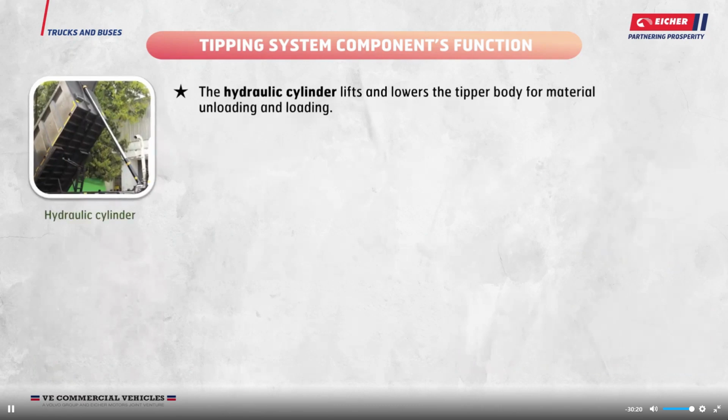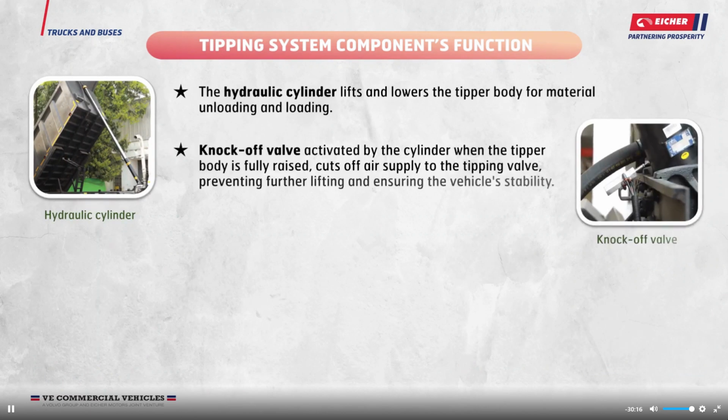The hydraulic cylinder lifts and lowers the tipper body for material unloading and loading. Knock-off valve activated by the cylinder when the tipper body is fully raised, cuts off air supply to the tipping valve, preventing further lifting and ensuring the vehicle's stability.